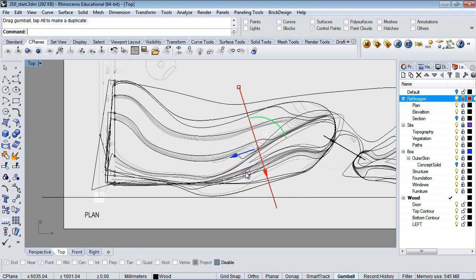Really accurately, my first control position would be up here where it's starting to make that transition. And then the next cross-sectional curve would be down here in this transition. So anytime I have some complex area where I really want to control how the geometry is changing in tight ways, you want to add detail. So that means adding cross-sectional curves. Okay?